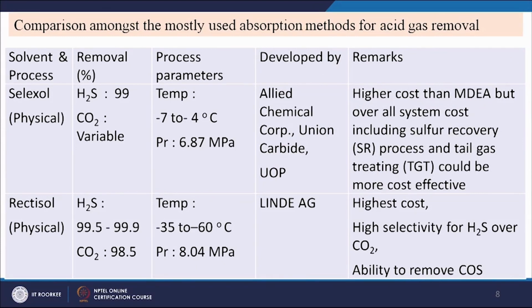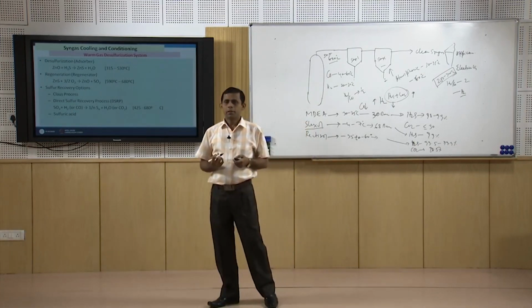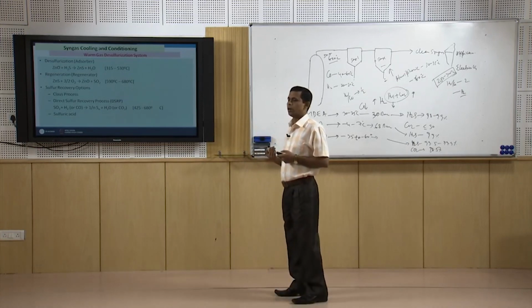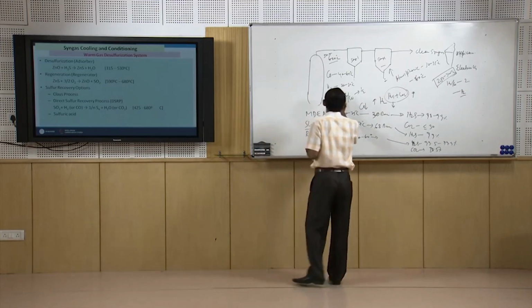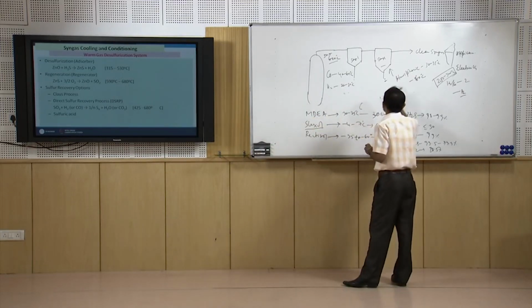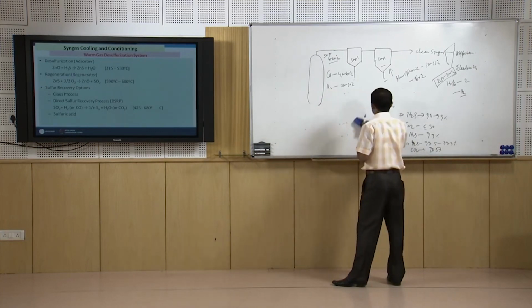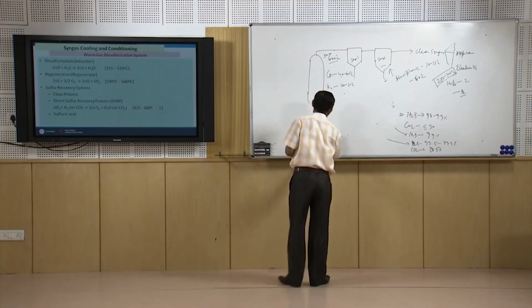Now, we will see the mechanism of syngas cleanup at hot conditions or warm cleanup of the syngas. At high temperature, if we use some metal oxides, then H2S is converted to the metal sulphide and steam.